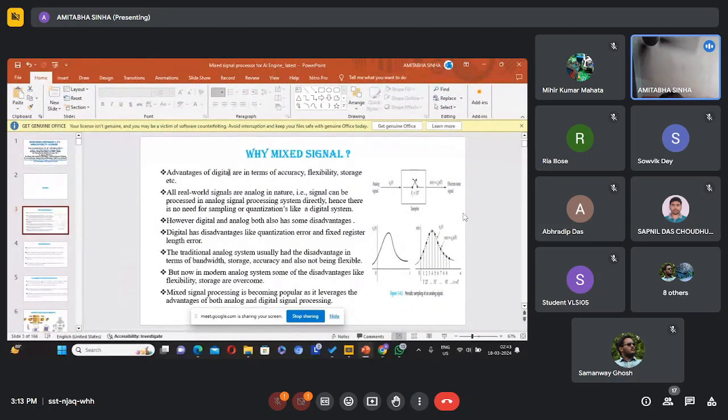And in terms of accuracy level, in any case, digital is always higher in accuracy compared to its analog counterpart. The reason being, analog circuits are governed by resistors, capacitors, inductances, etc. And you cannot get the exact value of resistors or capacitance. Moreover, due to change in temperature and humidity, the value of the resistors gets changed.